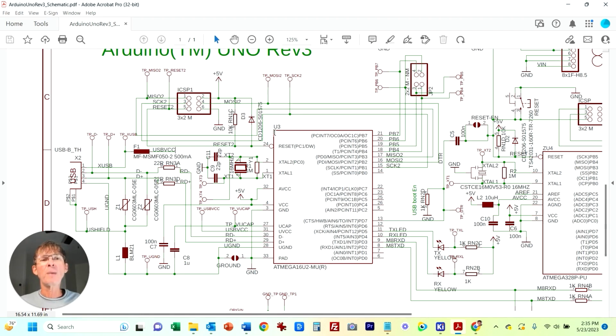A leadless package is a type of chip where the pins are on the bottom side and you can't actually see them or make contact to them once the part is soldered down. So you need test points, because otherwise you can't probe any of those. On packages with leads, you can just probe the pin, although the test points are still nice because you don't have to worry about touching two adjacent pins and shorting something out and causing damage.